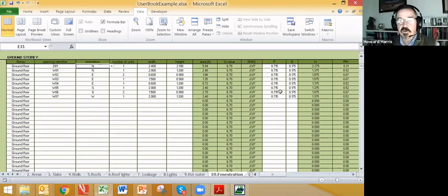We do need two further bits of information for you to provide the model. It is the p-value, and this, if you've been on the training, you'll recollect, is your projection distance. It's the distance from the line of the glass in the wall to the extreme edge of the shading device.